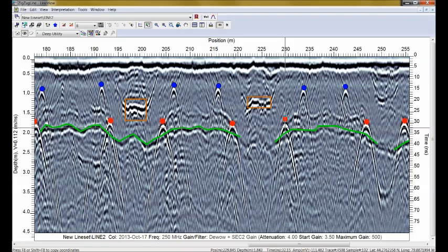And notice where the red interpretation appeared. It appeared way up here above. It wasn't actually anywhere near where I clicked. So when you add an observation, it does not necessarily appear exactly where you clicked. It jumps to the optimal location based on the pre-processing that we've done to the line. So where the observation appears on the hyperbola is actually based on your selection of where you'd like the picks to be.